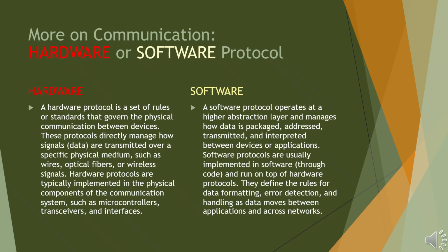perfect the software is. On top of this lies the software protocol, which defines how information is structured, addressed, and verified once it is transmitted over the hardware link. The software protocol specifies data framing, where a message starts and ends; addressing schemes, identifying which device the message is for, like I2C addresses or Ethernet MAC addresses; command and response format, defining what the data actually means; error detection